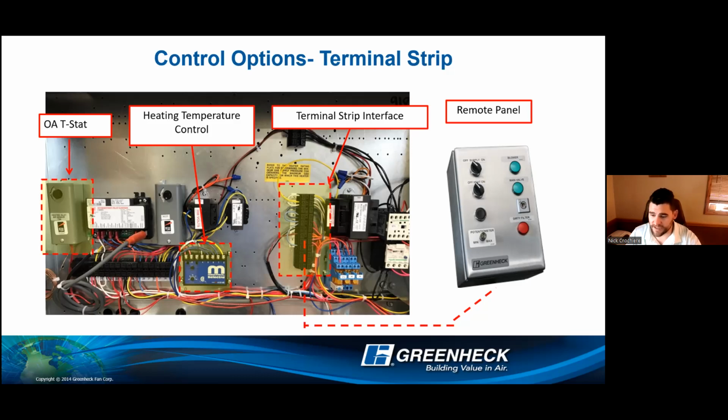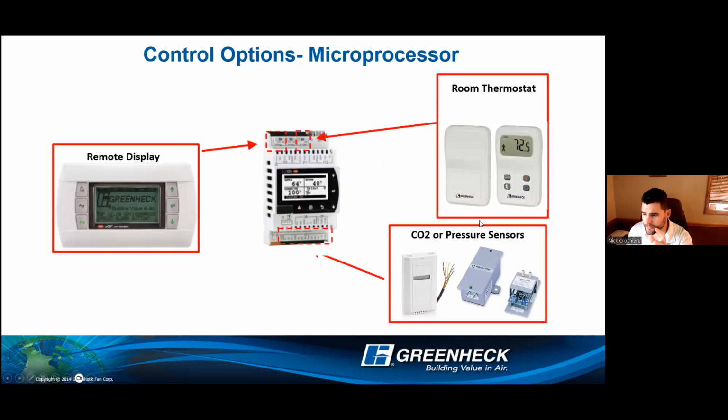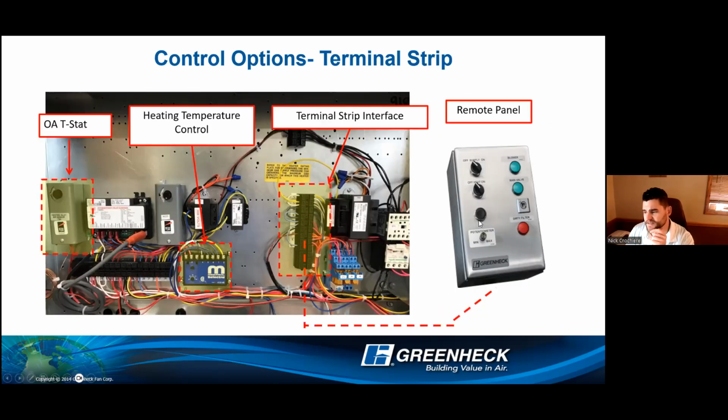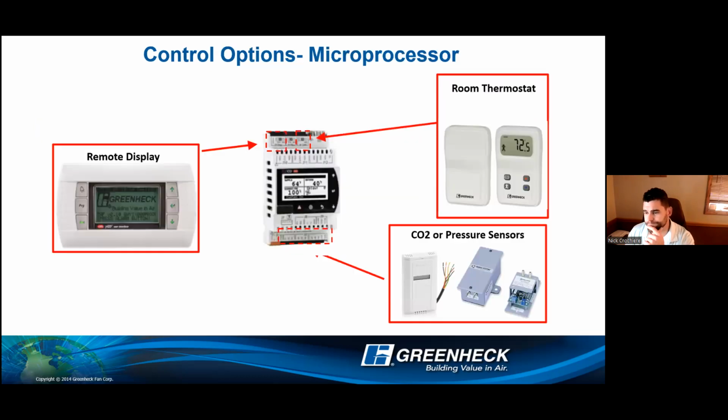Happy technician means a good startup and a good rapport, especially when they're working on your equipment. And then on the right side there, remote panel. That would be the option you can select when you're talking about space heating, is it's going to have a room temp sensor in that panel. We have two options: an industrial, which is painted, and a severe duty, which you can see in that picture. That is a stainless washdown rated NEMA 4X, NEMA 12 panel for those like wastewater treatment or other applications where you may need it.